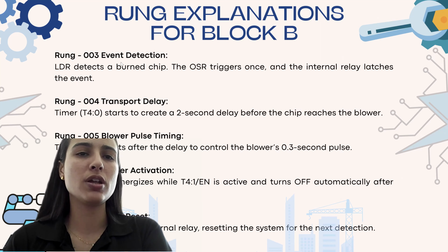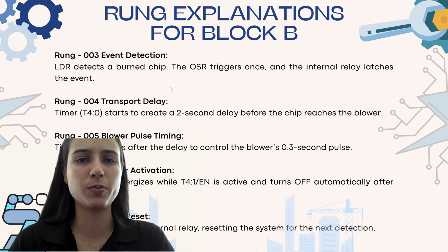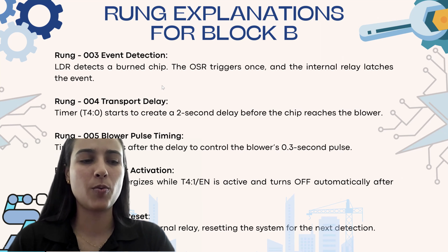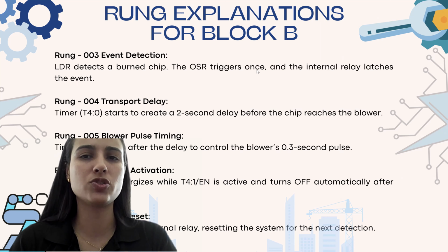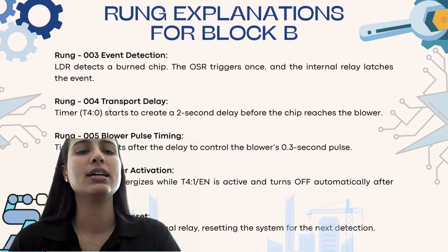Rung 003 is the event where the LDR detects the burnt chips. The OCR triggers once the LDR is activated, meaning that once the LDR is activated, it will turn off, but it will latch the blower. So the OCR triggers once and the internal relay latches the event.